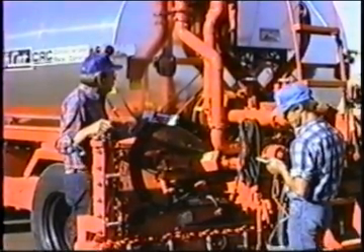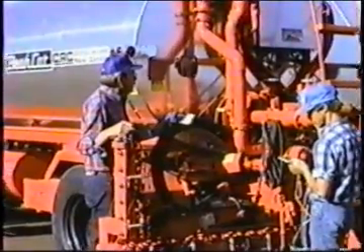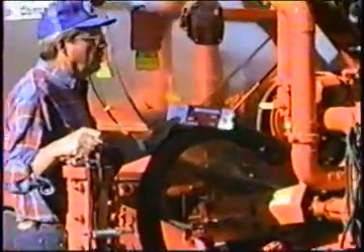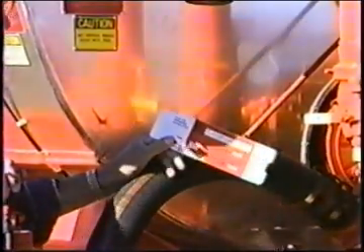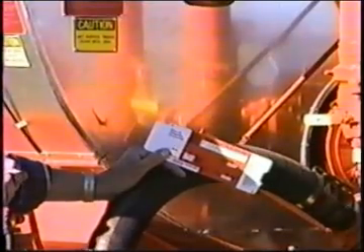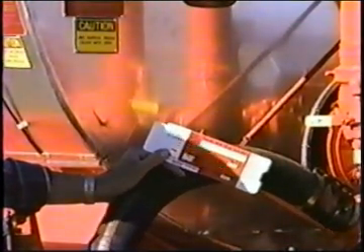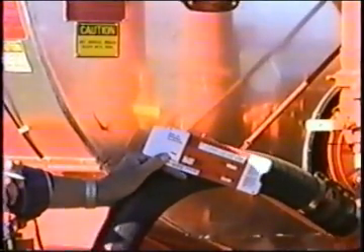Let's say that this particular truck has number 3s in it. We've set 0.25 on 400 feet per minute. In the number 3 nozzle window, I see 8 psi. Okay, 8 psi is going to be the pressure created by this size nozzle, a number 3 size nozzle.